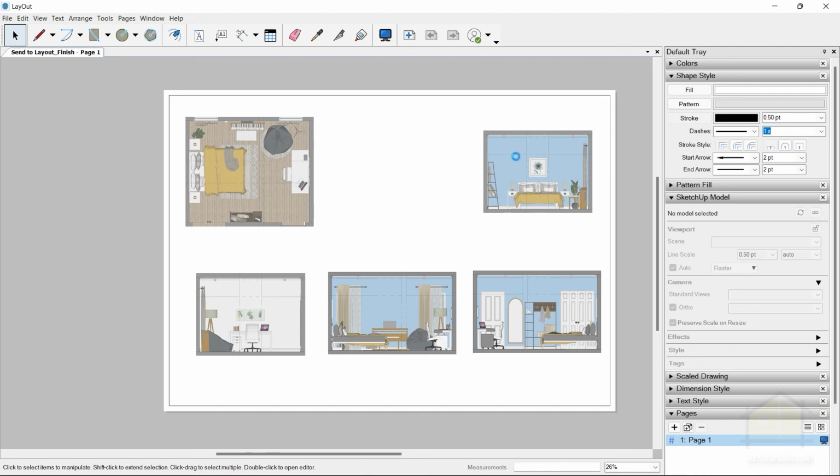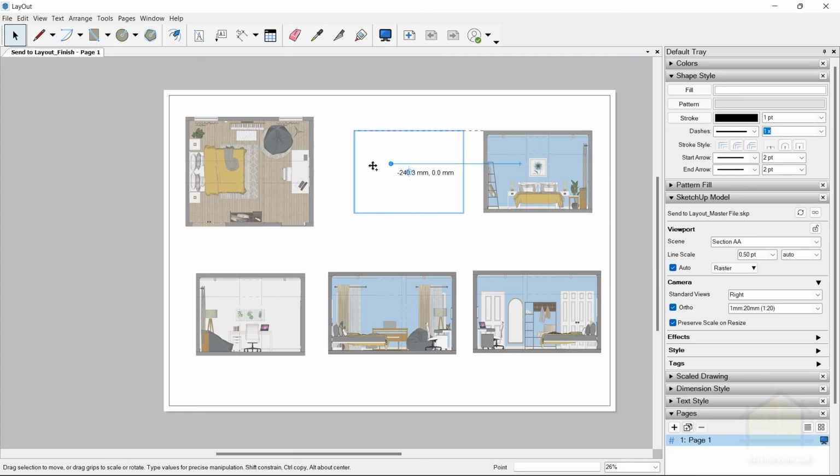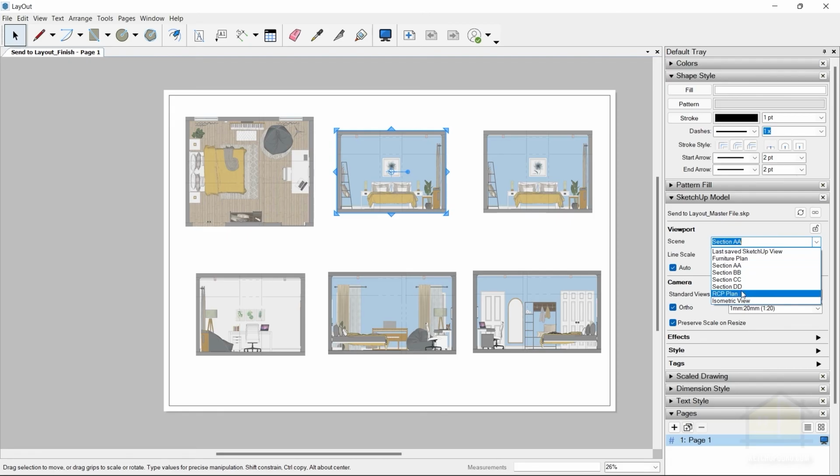All right, I'm also going to create an additional view because I can see that I have enough space in this page. So I'm going to press Ctrl, then move this to the left, hold Shift to lock it to that line, release the mouse key, and then release the keyboard keys. Then I'm going to select this and change it to RCP plan.